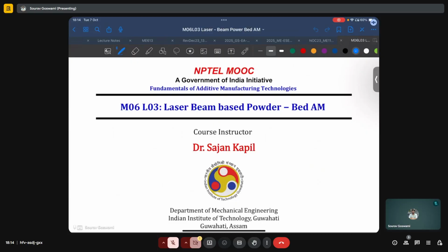On the other hand, if you are working with something like a phase field model or a very highly reliable fluid flow model, it will be able to recreate heat transfer and flow currents inside the melt pool. Based on the resolution we are looking at, it may also be able to predict segregation profiles or dendritic features such as primary and secondary dendrite arm spacing. But then it will only be limited to very small domains and will not really be applicable at part scale, because the calculations will simply become intractable despite the use of state-of-the-art computing facilities. And so there is a need for multi-scale models of AM processes.